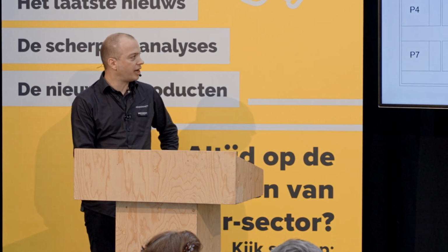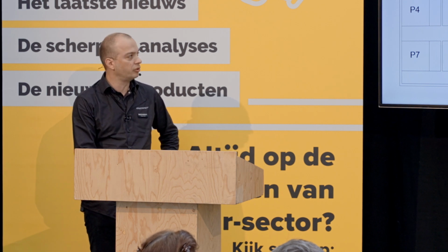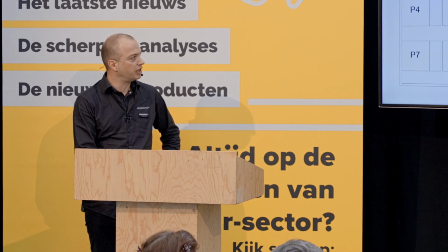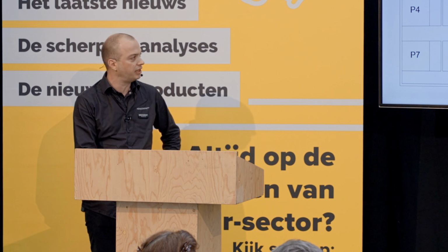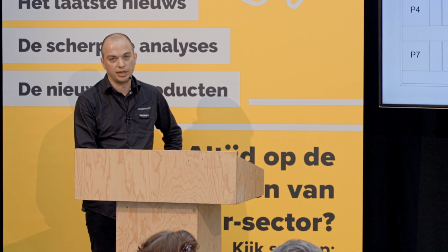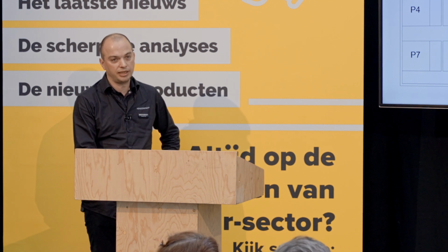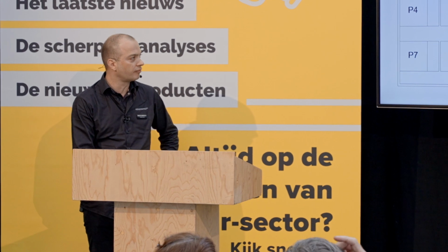What is also important is to put the solar array in as many positions as possible on the roof to capture the different flow effects. The flow in the corner of the building is very different from the flow at the roof edges, and again different from the flow in the deep roof interior. That's why we put the solar array in 7 to 9 positions in general on the roof.